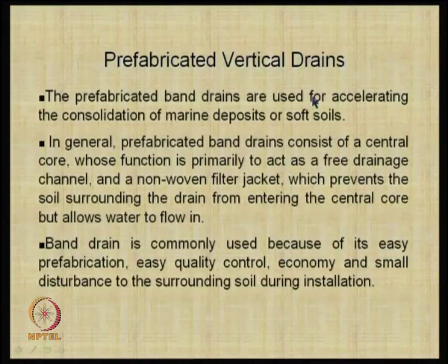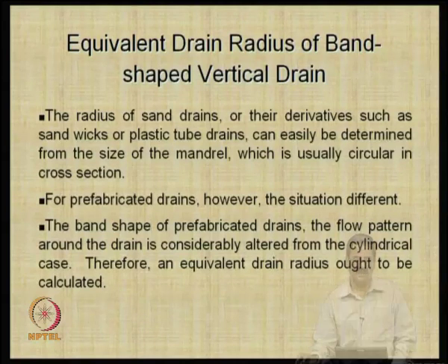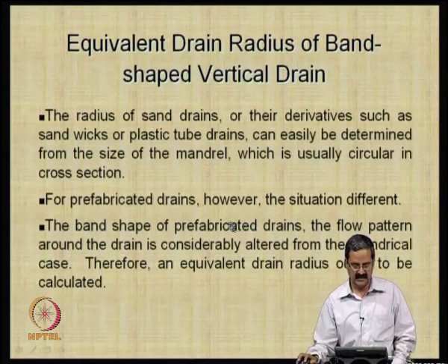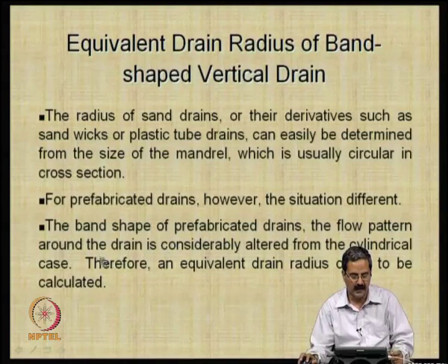As I just mentioned, PVDs are much more comfortable to use because of the ease of fabrication, quality control, and economy, and the sample disturbance to soil is very little during installation. This is another important point one should realize: for sand drains we had an equivalent diameter, and now since the shape of the drain is more of a rectangle, the flow pattern around the drain is considerably altered from the cylindrical case.